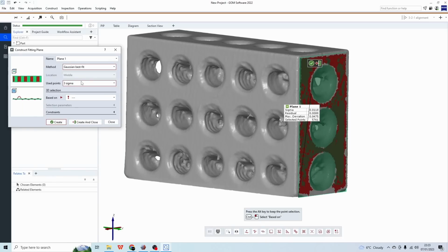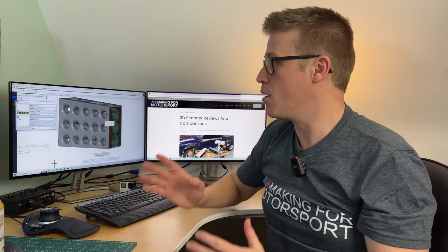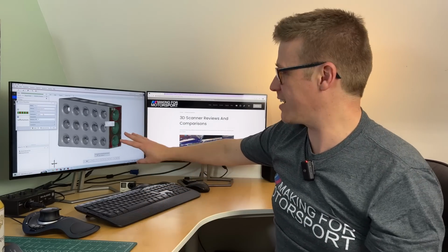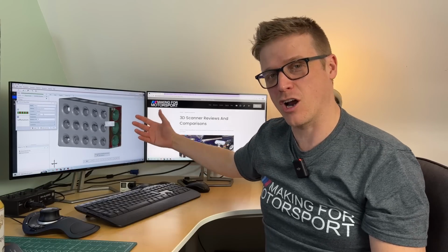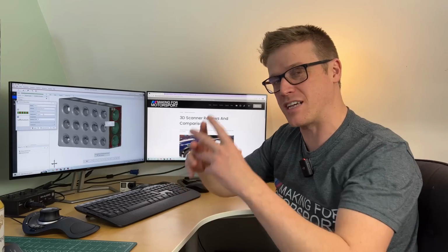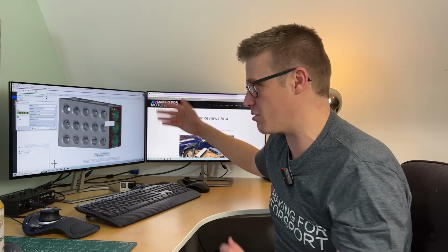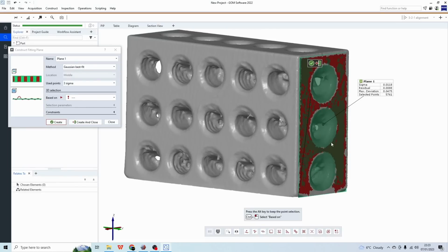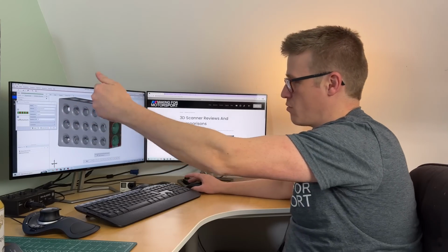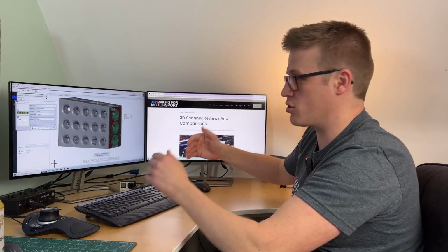So what's sigma? Sigma is a standard deviation. Again, we're not going to get into the huge amounts of stats here because this video will go on, but just trust me, it's selecting all of the relevant points that are close enough to the point that I selected and going, right, I'm going to look at all of these points and take these into account when I try to work out where the plane is on that surface. You can see the points that it's selecting, red are below it and green are the other side. So you can see how they fall either side of the plane.